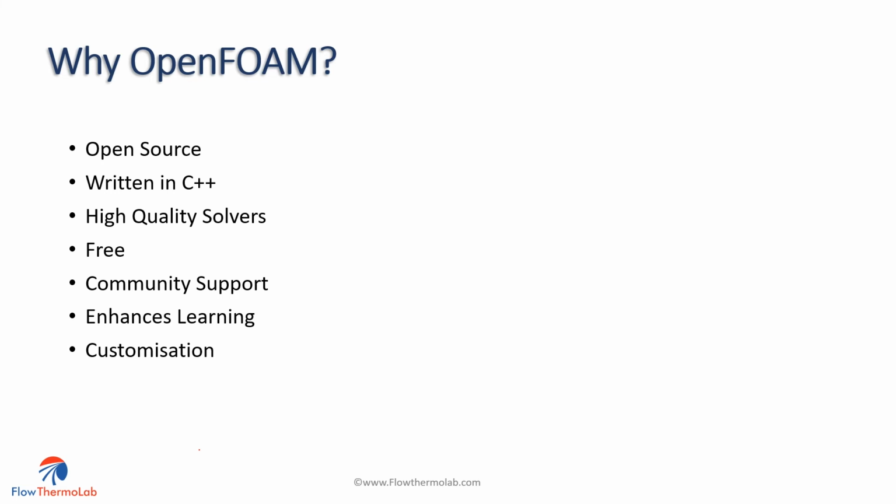And as I've touched on, for users with programming skills in C++ and those who understand perhaps numerical methods or even just basic concepts in OpenFOAM, we have the opportunity to develop and implement custom solvers, boundary conditions, turbulence models, other features such as post-processing, function objects, that sort of thing. And this level of control allows us to customize simulations to specific requirements or research objectives, for example.